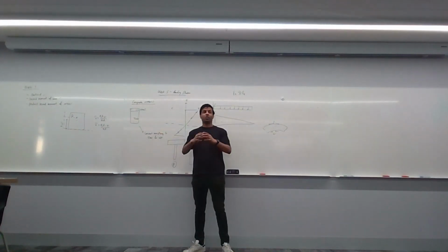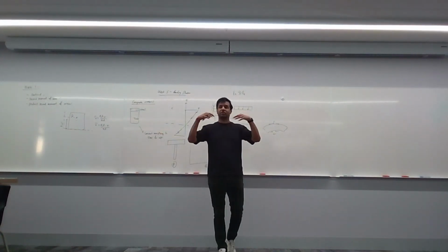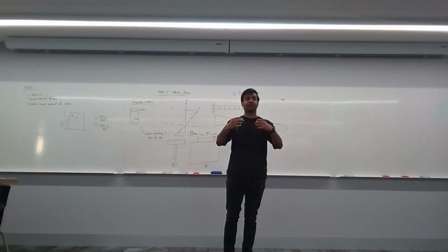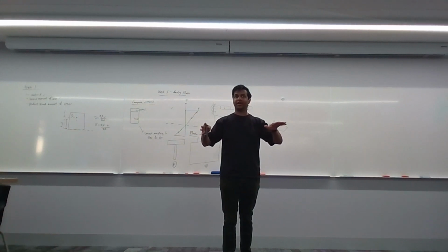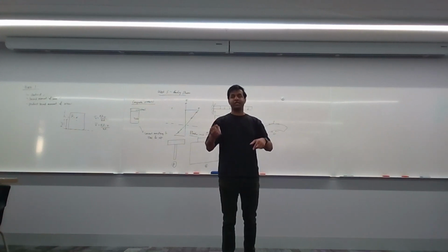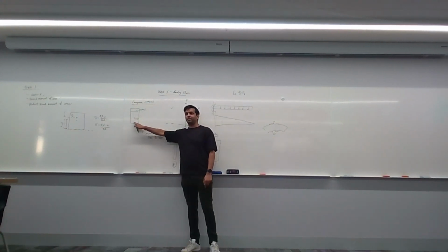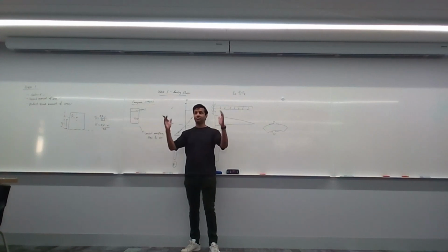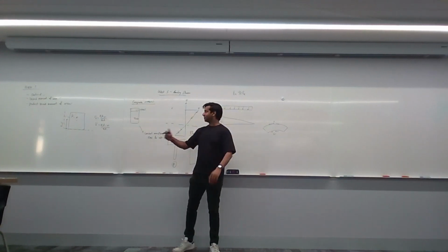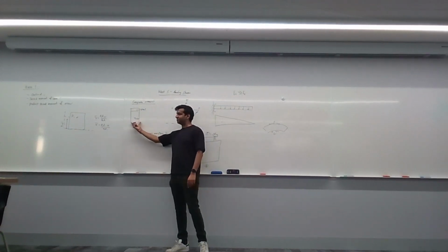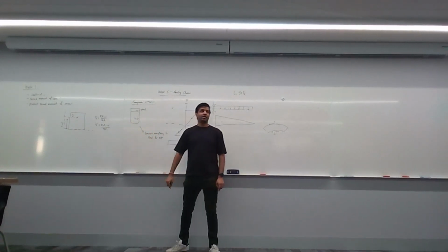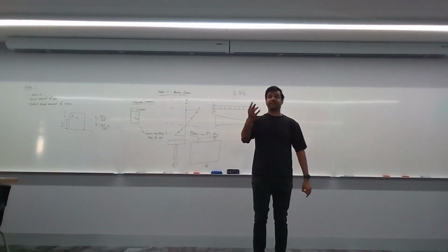So remember, this is the concept you've got to remember. The weaker material needs more volume to do the same job as a stronger material, right? So if you're converting the weaker material, timber, to the stronger material, you shrink it. Because a thin strip of steel this way will do the same job as a thick piece of timber this way, okay?